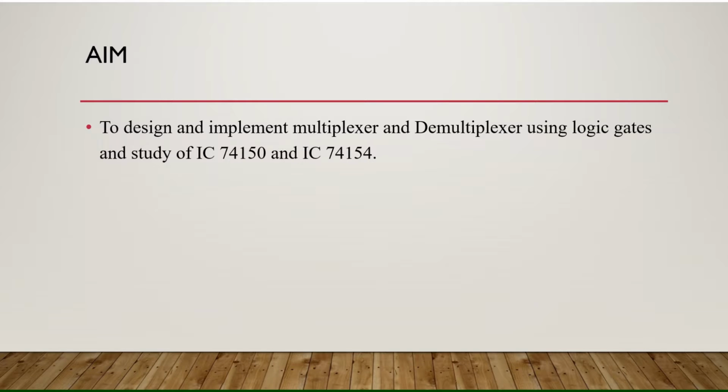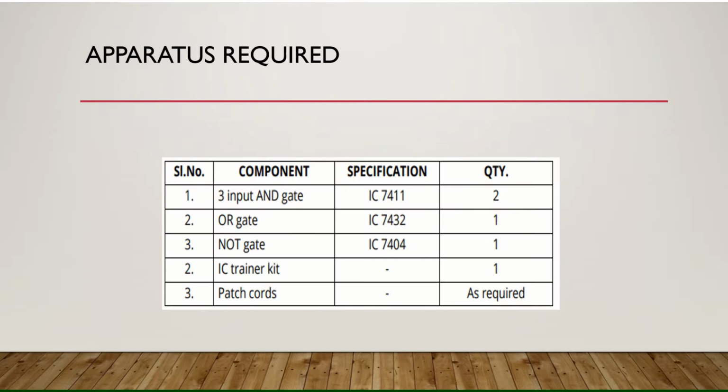Its aim is to design and implement the multiplexer and demultiplexer using logic gates and study of IC 74150 and IC 74154. Here the apparatus required is 2 3-input AND gates, 1 OR gate, 1 NOT gate, 1 IC trainer kit and patch cards as required.